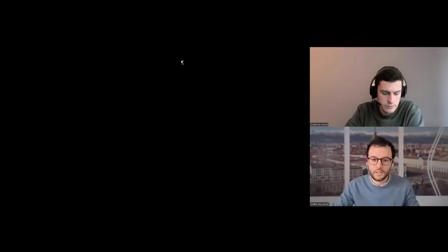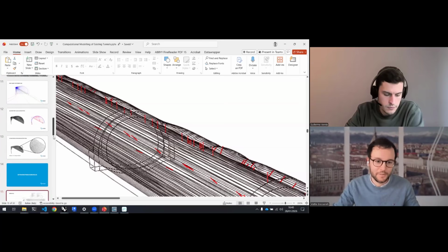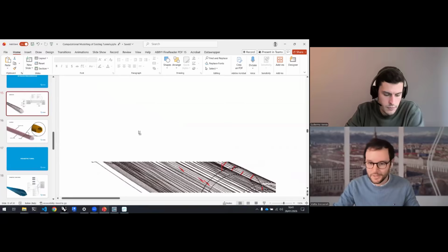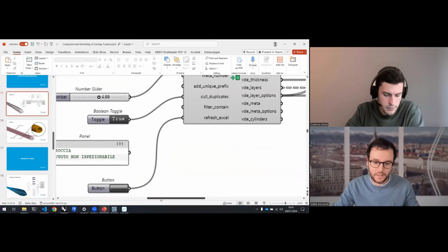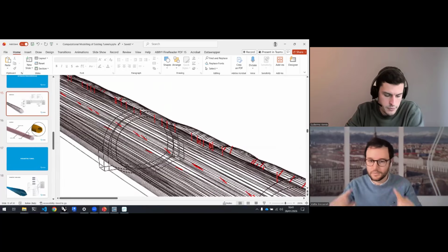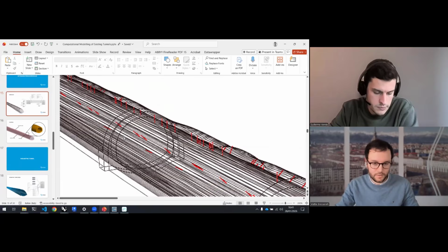Okay. So as I was mentioning, the Excel file is pretty self-explanatory. Then we import it in Grasshopper with this component, basically a read Excel. And then this just places those layers as cylinders. It attaches them to the intrados. So the intrados, we got that from the survey. And then by positioning these in 3D, we can also get all the 3D coordinates and points of the different layer separations and vectors that define the directions.